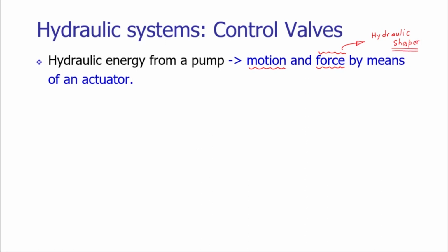is a material removal machine. In this machine we have a relative motion between the tool and the workpiece. The workpiece is stationary and the tool is reciprocating, it is translating over the workpiece material. That translatory cutting motion is developed by the hydraulic system, the hydraulic energy. So the required force will be generated by the hydraulic system in the shaping machines.